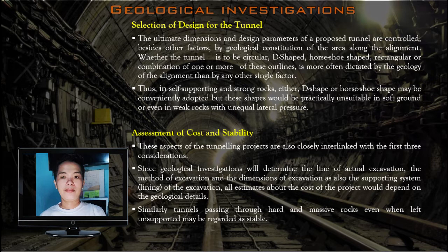Assessment of cost and stability. These aspects of the tunneling projects are also closely interlinked with the first three considerations. Since geological investigations will determine the line of actual excavation, the method of excavation, and the dimensions of excavation, as also the supporting system of the excavation, all estimates about the cost of the project would depend on the geological details. Similarly, tunnels passing through hard and massive rocks, even when left unsupported, may be regarded as stable.